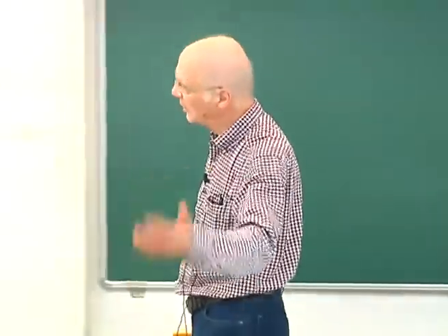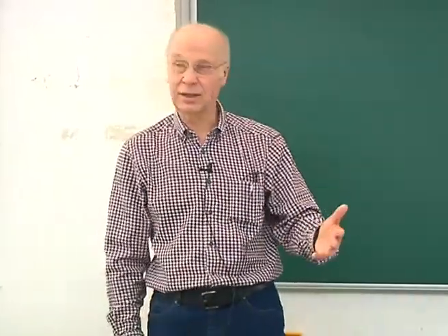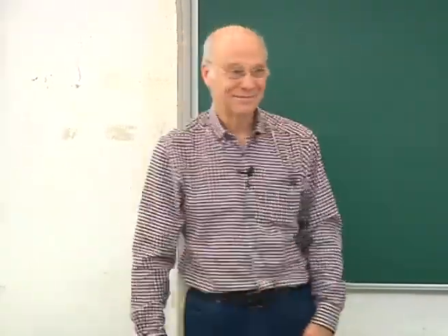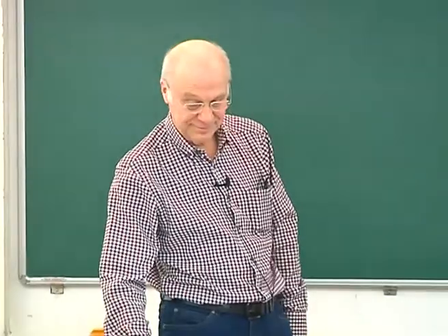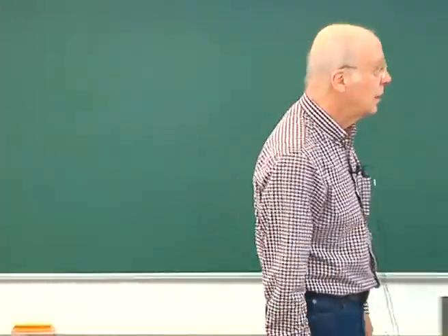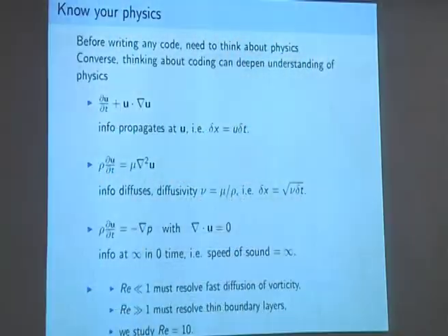So this is the first hint that pressure is not a friendly thing for the computing. Okay, so there's a Reynolds number, which I hope you are okay on. We'll define it in a minute. There's various things that happen. At low Reynolds numbers, vorticity diffuses very rapidly, and you work in a quasi-static situation.